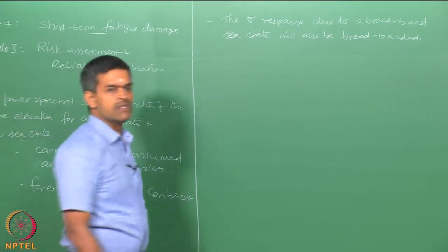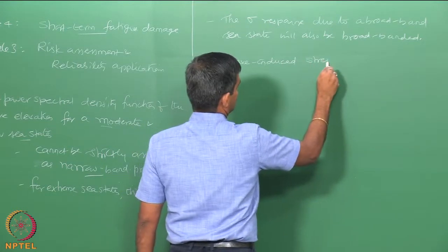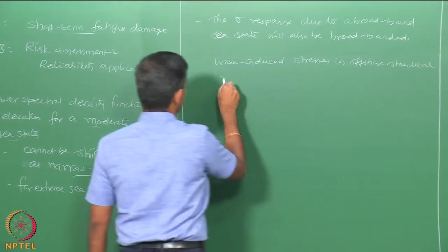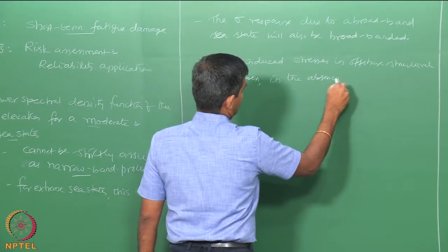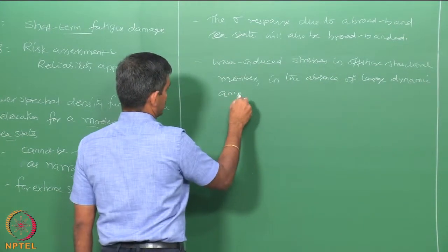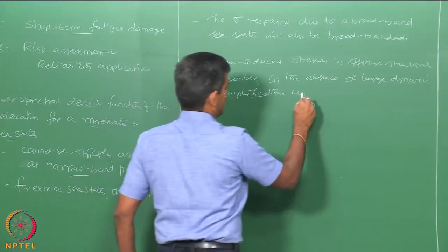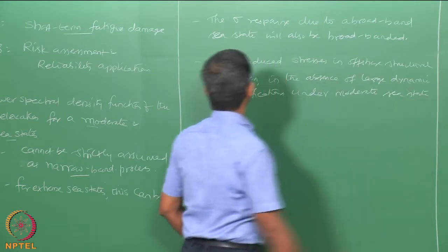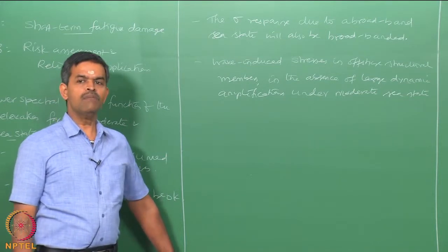Therefore, the wave induced stresses in offshore structural members, to be very specific, in the absence of large dynamic amplifications, which are exposed under, let us say, moderate sea state, will continue to remain as broadbanded, which cannot be ignored in fatigue calculations.